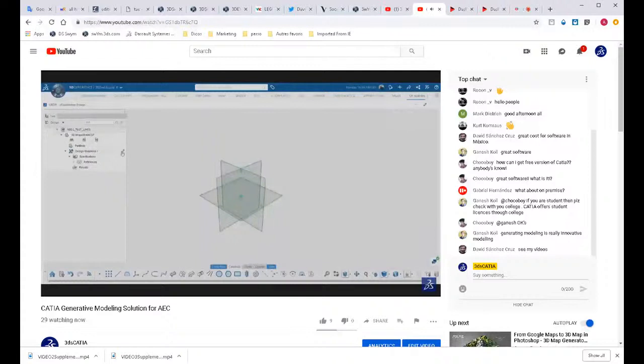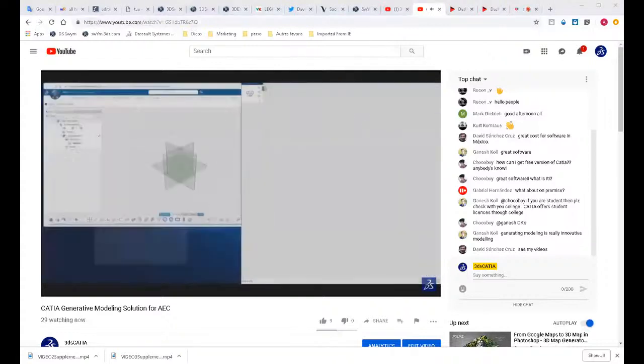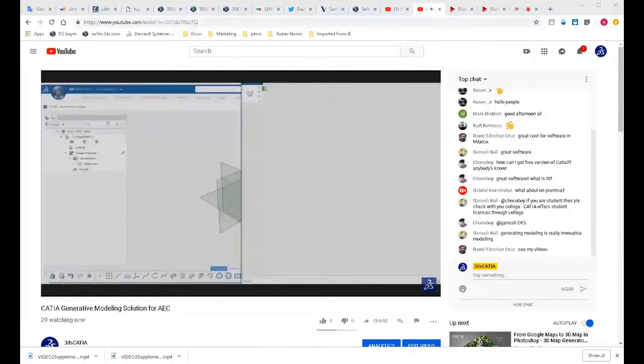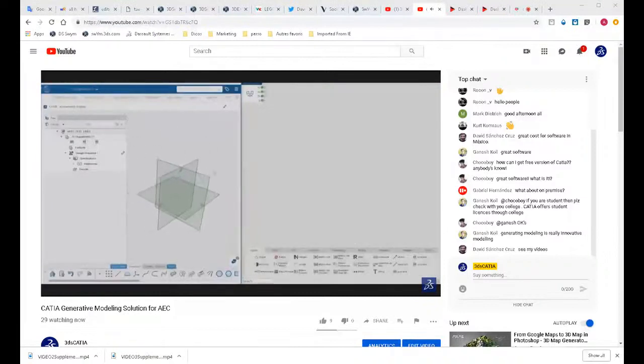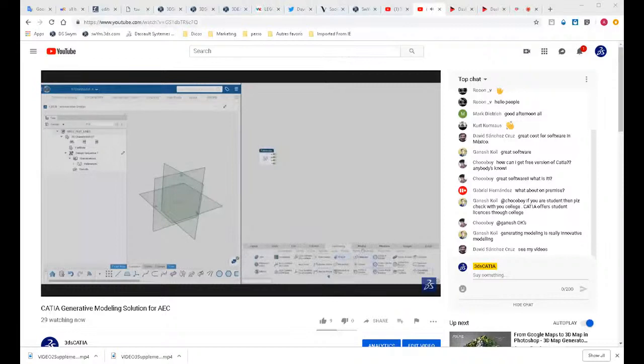Here I'm going to launch the design sequence, which is the visual scripting interface that has just appeared on the right. Just by clicking on design sequence, edit, it launched what we call the canvas. At the bottom you have a lot of operators that will help you to design your project.